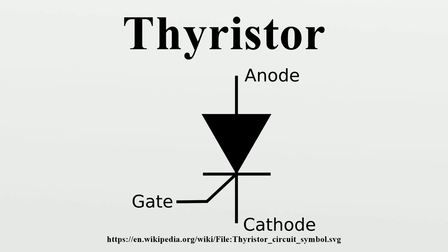Originally, thyristors relied only on current reversal to turn them off, making them difficult to apply for direct current. Newer device types can be turned on and off through the control gate signal. The latter is known as a gate turn-off thyristor, or GTO thyristor.